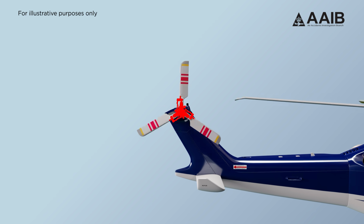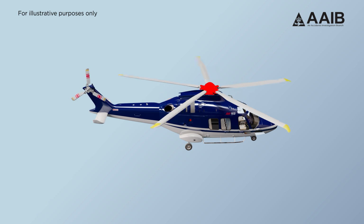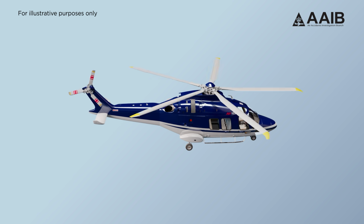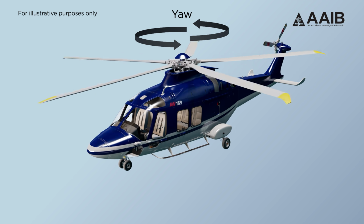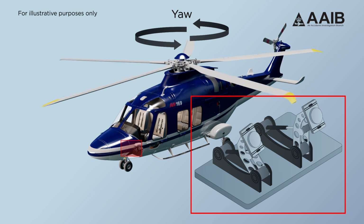The AW169's tail rotor produces a force opposing the torque of the main rotor in order to control its effect. To maneuver the helicopter in yaw, the pilot can increase or decrease this force by alternately pressing on the pedals.